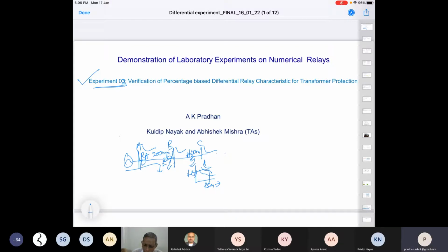The level of current for these two faults is very difficult to discriminate by the overcurrent relay. So this relay will be in confusion whether the fault is in the BC section or the AB section because there is no clear demarcation.